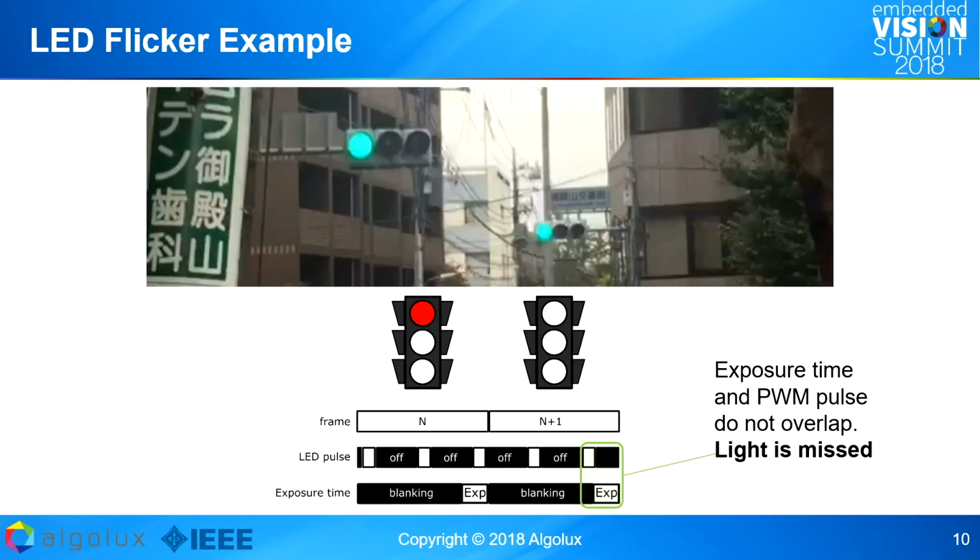So let's start and go through the individual efforts, just to give you an overview, just to walk you through what is being addressed in the standard. So LED flicker is a dynamic artifact of sampling LED illumination signals in the wild. Most of our traffic signs, illumination signs, outdoor illumination are LED-based these days, and LEDs are driven with pulse width modulation. We have short pulses, unfortunately exactly at a frequency that's pretty close to the sampling frequency of a camera, like 60, 70 hertz. They're pulsed and switched on and off with a very short duty cycle.